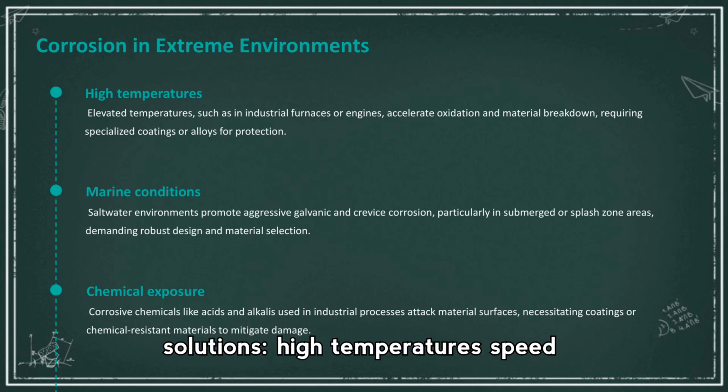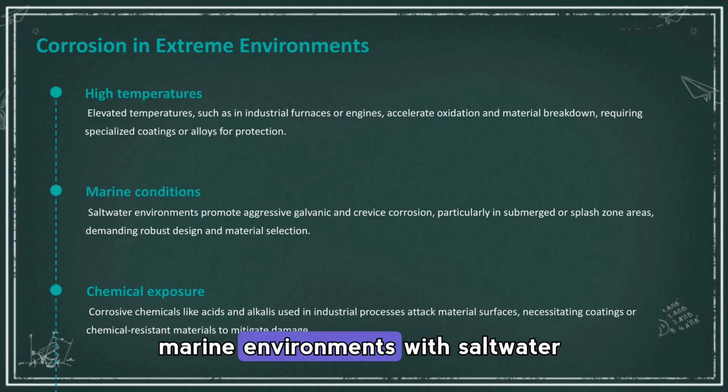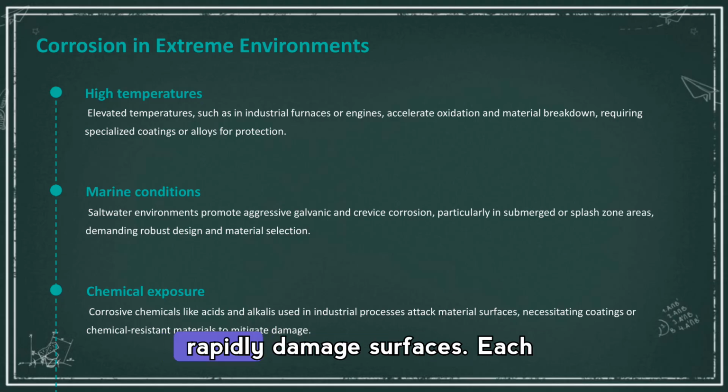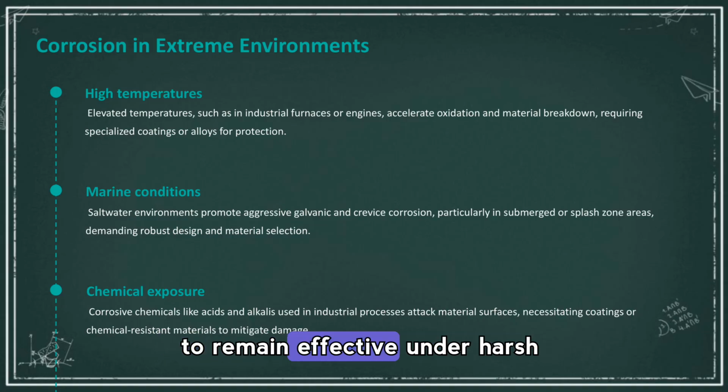High temperatures speed oxidation and material breakdown. Marine environments with saltwater promote aggressive galvanic and crevice corrosion, and chemical exposure from acids or alkalis can rapidly damage surfaces. Each scenario requires tailored materials, coatings, and maintenance regimes to remain effective under harsh service conditions.